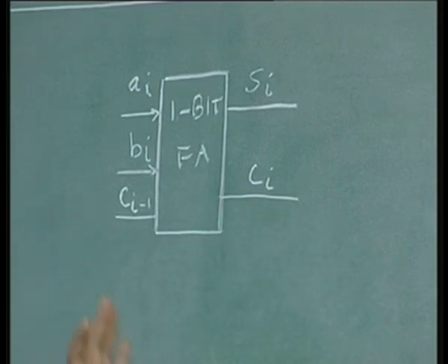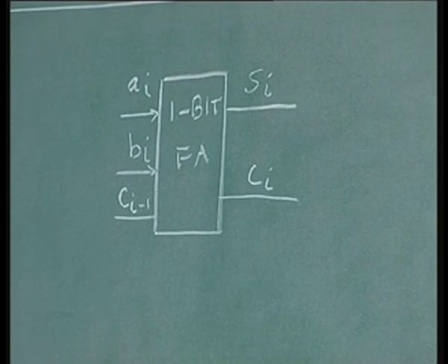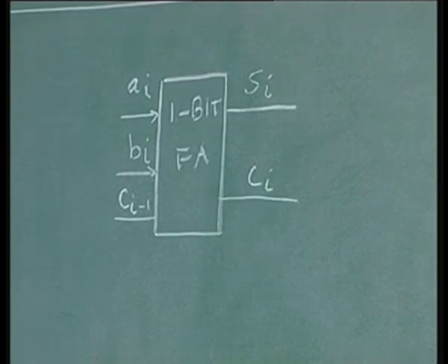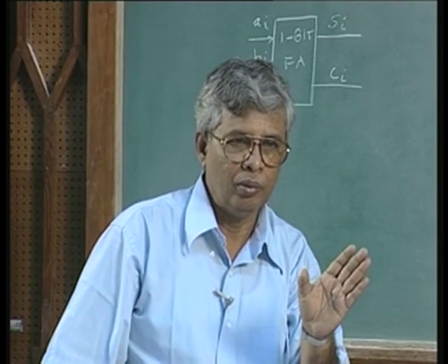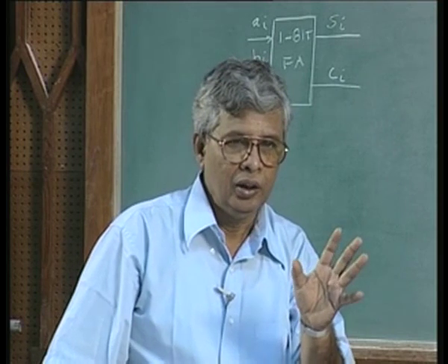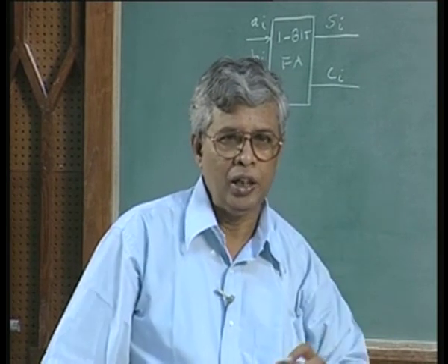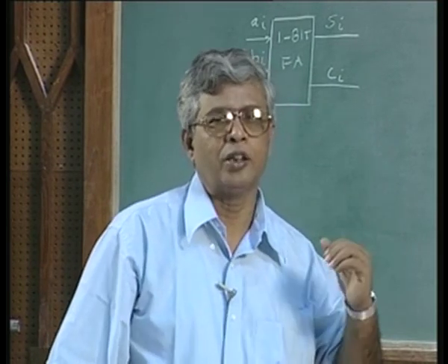This is exactly the concept of sequential circuit we have seen in the last lectures. In the last 2 lectures we talked about the sequential circuit requirement being a device or a circuit element which will store a value from the previous clock period and give it as the input to the system during the next clock period.